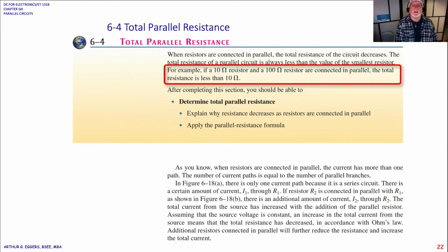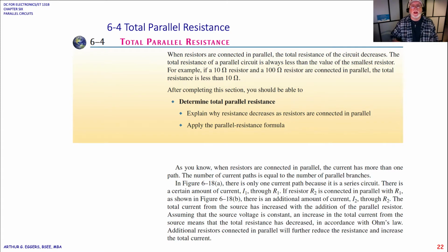less than 10 ohms. So we're going to start looking at these circuits and say, okay, we need to calculate the total resistance in this parallel circuit, and I know that the equivalent is going to be smaller than the smallest resistance in the circuit.